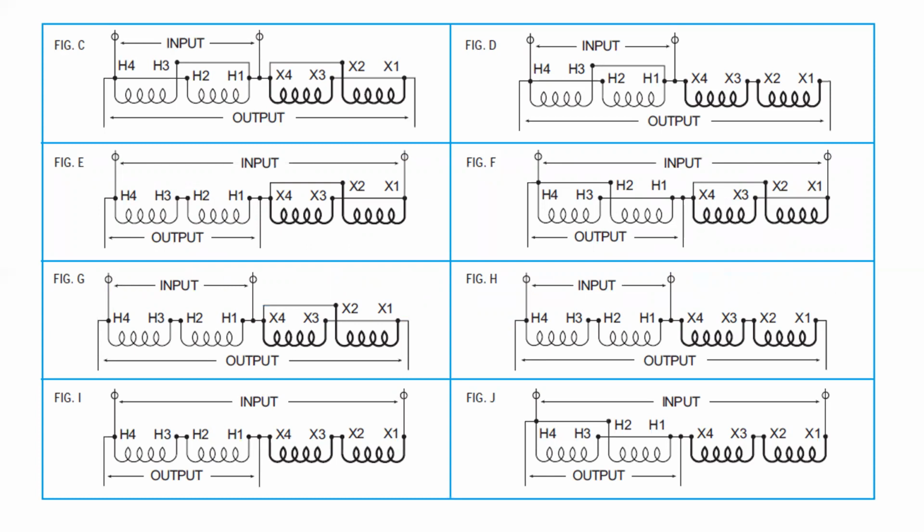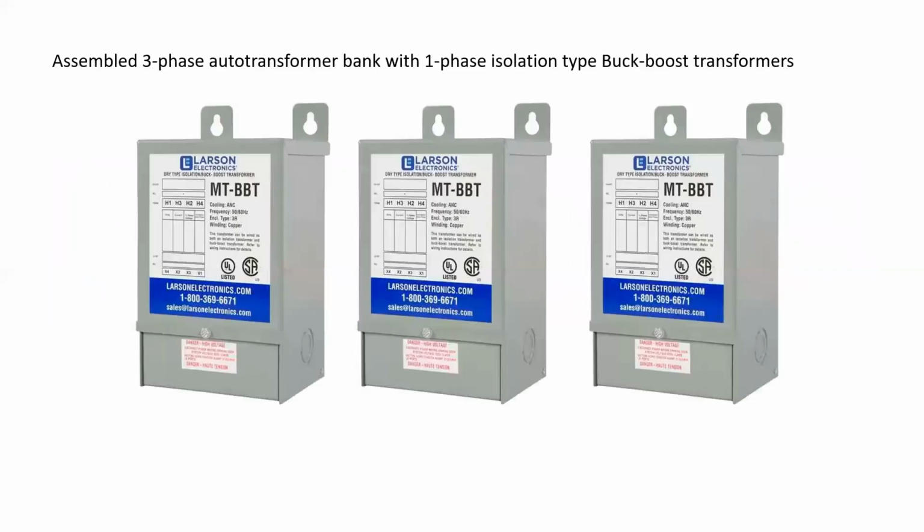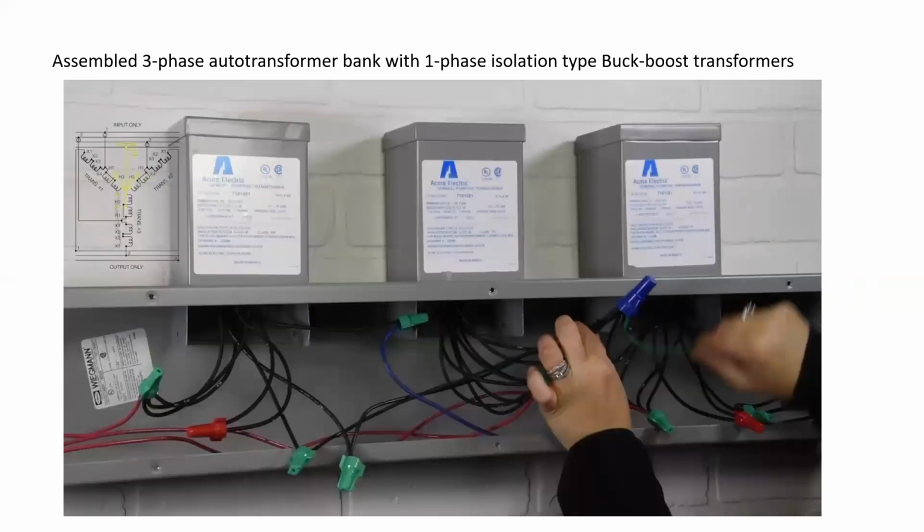And so the manufacturers take this into account and provide additional diagrams that show how this transformer could then be connected into a three-phase auto transformer bank with either a Y or an open delta formation. Here's a few of the diagrams from this particular manufacturer showing how we would do this connection.